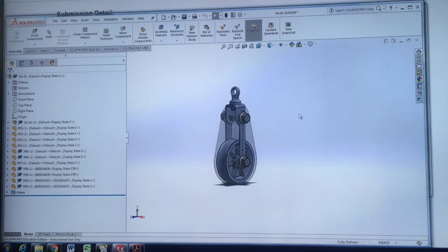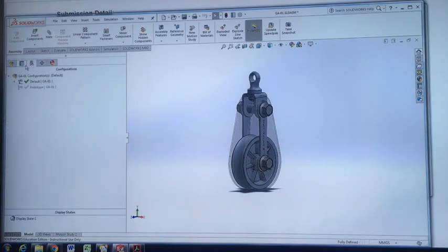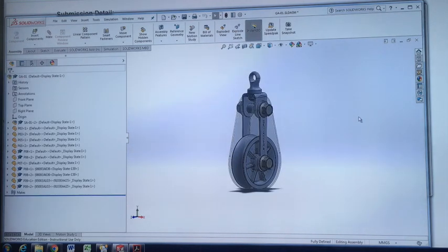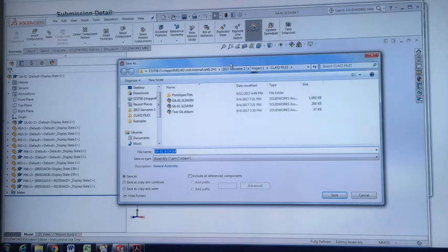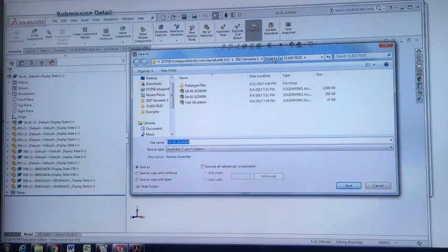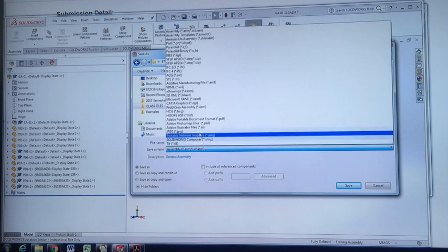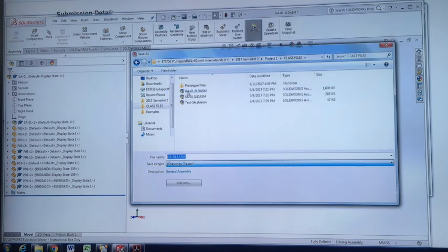Alright, so with creating an eDrawings file, if you've already done your exploded view and added materials, which I've skipped for now, but don't worry about that. There's a publish to eDrawings button here, but just as easily, or probably better, is to do Save As. All you do is change the file type to eDrawings. So if you're in a part or an assembly, it'll automatically go to whichever type.